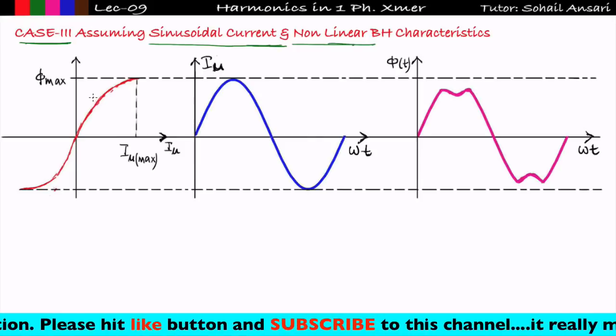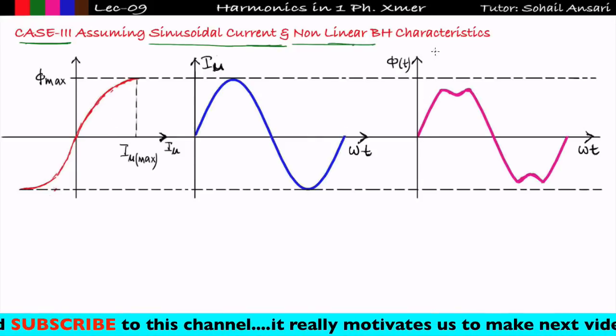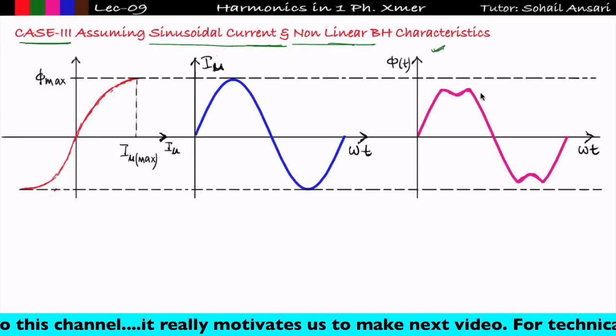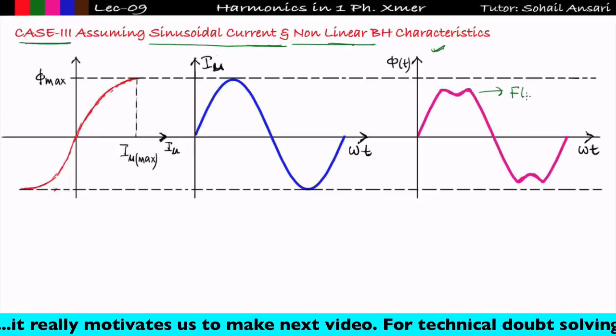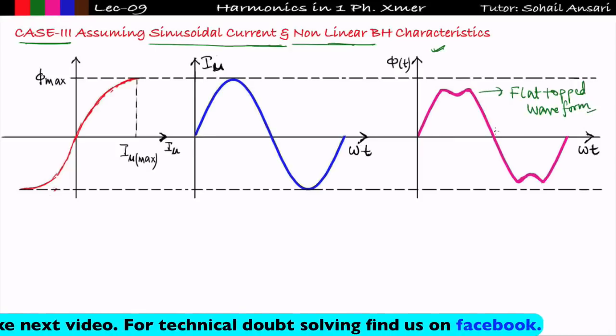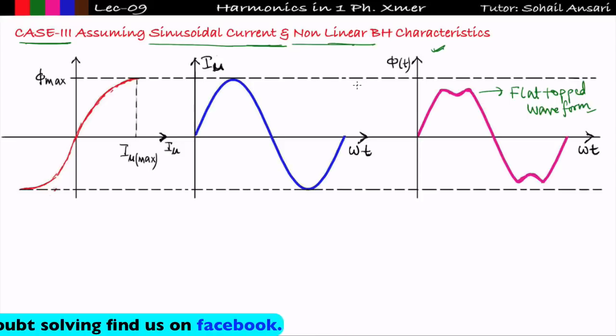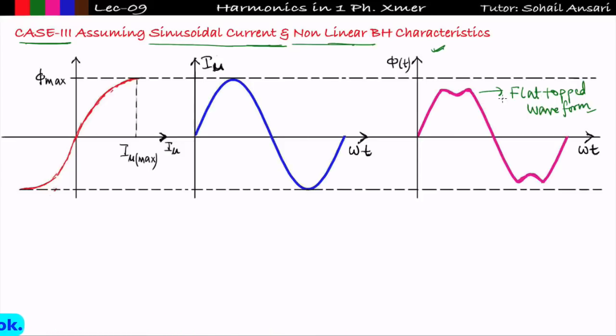So you can do the procedure same like in case 2 and you will get the value of phi t like this waveform, which is the flat topped waveform, same as case 2. In case 2 we are getting the waveform of I mu, but here I mu is sinusoidal and we are getting the waveform of phi t. Now the point is, since the phi t is flat topped because of sinusoidal magnetizing current and non-linear BH characteristics, we are getting the phi t is flat top.